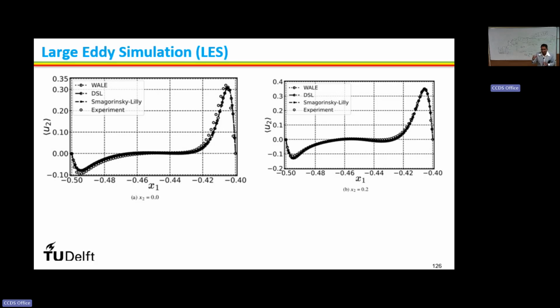So again, it's based upon the experience of the user. It's a heuristic approach. You need to decide judiciously where to use the fine grid and where to use the coarse grid. But definitely, the coarse grid DNS you can try, but again your grid needs to be sufficiently resolved to capture those eddies, right? So that's why, with a sufficiently fine mesh, first we do the RANS simulation.